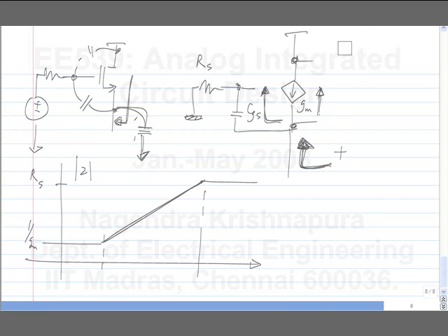But let's say even without using phasors, what is the first thing you hear about inductor and capacitor? Long back, when you first hear of an inductor, even before that, I think. The capacitor holds what? Voltage. You hear that the capacitor voltage cannot change instantaneously. Similarly, an inductor current cannot change instantaneously, because a back EMF is developed that will resist the change in flux.